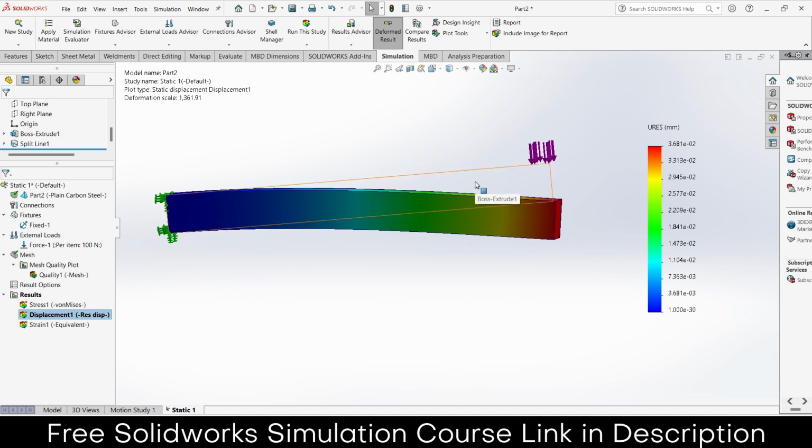Here is the thing: when you do the simulation in SolidWorks, it shows 2000 or 3000 times the actual displacement. The reason is so that you can visualize where the deformation is actually happening. For example, 10 to the minus 2 is a very small deflection, you can't see it with your naked eyes. That is the reason SolidWorks shows the deflection 3000 times the original.